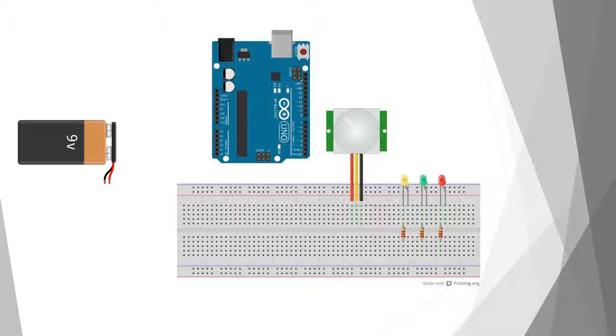Now every time we use an LED, we can't hook it up directly to our pin on the Arduino, because it will put too much current through the LED and it will burn out the LED and it won't give off any light. So what we have to do is put a small current limiting resistor in front of each LED, and we have put 220 ohms on each one here, running up to one of the legs. And it doesn't have to be 220 ohms, 330 ohms is a common one. You can use a little bit more, a little bit less, but just a low value like that. So now we have all our components in place and we're ready to start hooking things up.